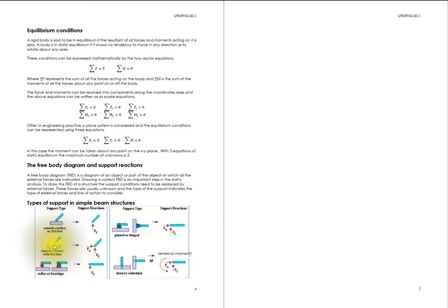In this particular case, we would imagine some sort of hinge. We're pivoting on a surface, and we're saying that particular contact point won't shift. There's friction or whatever keeping it in place there. So there must be some force going in the x direction, and because it's pushing down into the plate, we imagine there's going to be a force going in the y direction. If that plate was now smooth, then we wouldn't be able to have any friction in the x direction, and we would only have a force going in the y direction.